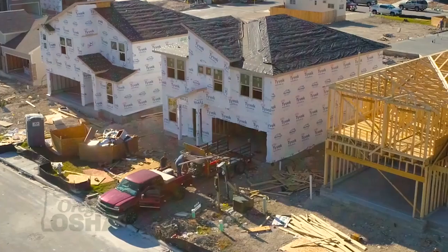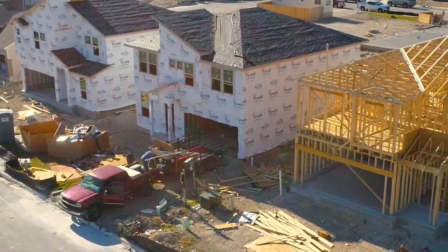So when it's feasible and when you can do that, I think that the idea is, to me, this is part of that hierarchy of controls, right? If we can stop somebody from actually falling over the edge and not have to recover them, I think that's going to be beneficial. It's going to be faster, it's going to be safer for your employees, and probably a lot easier for them to work. So I definitely think there's benefits to using that over fall arrest.